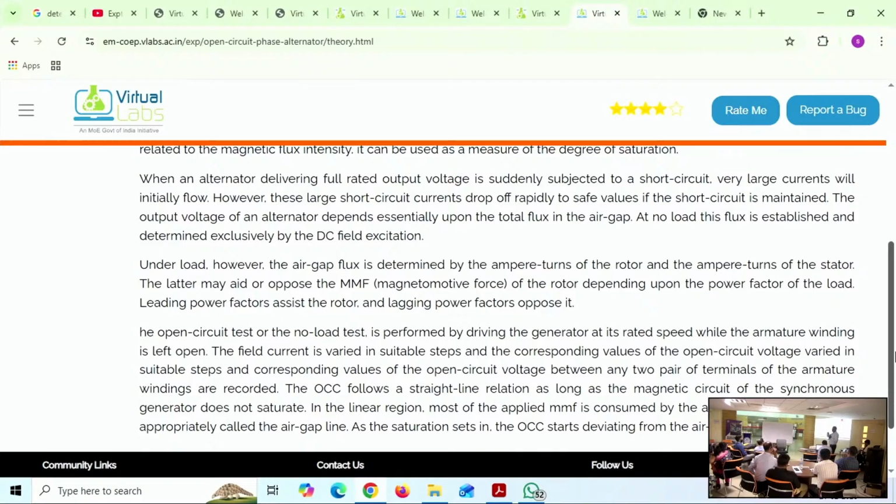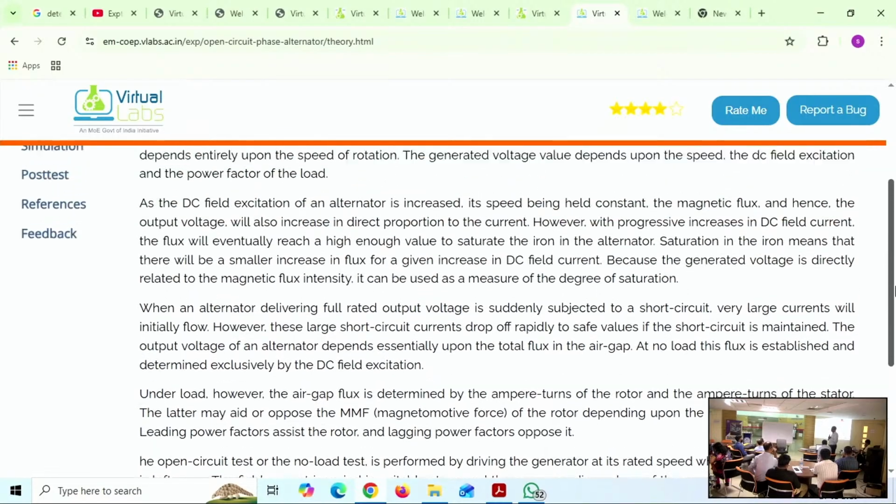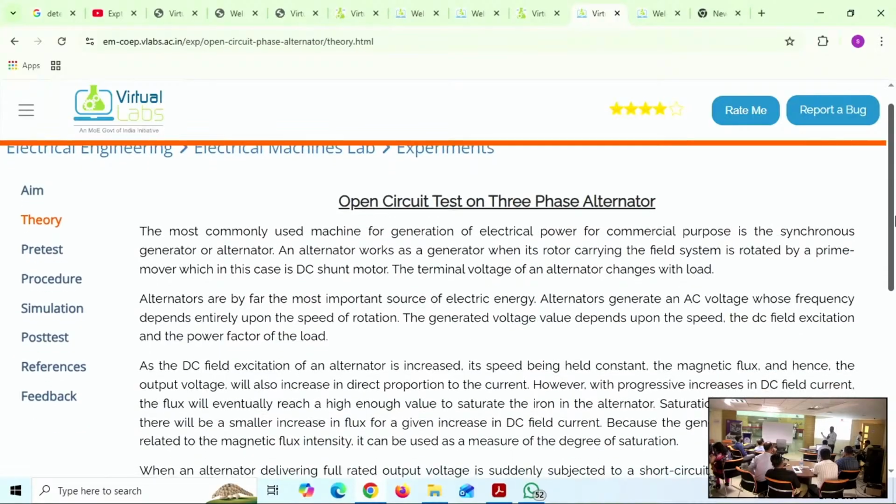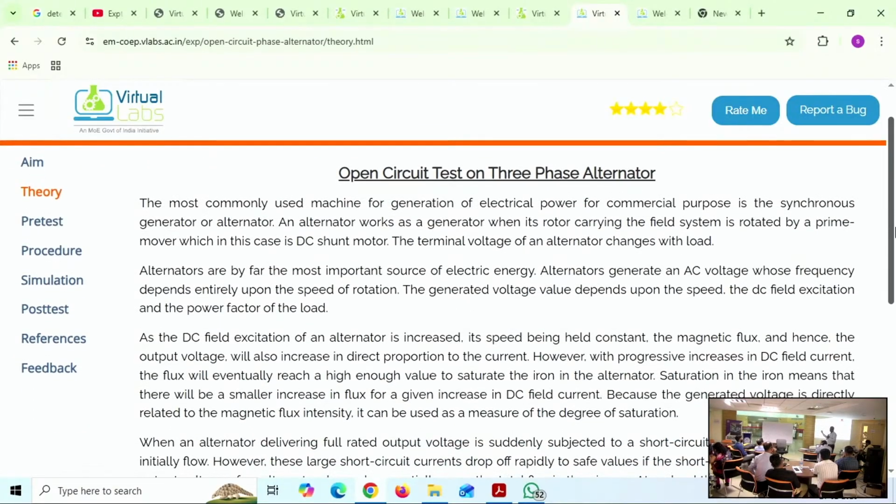That is how we better understand the experiments. One more thing, while connecting the meters: theoretically, ammeters must always be connected in series and voltmeters in parallel. Now practically, first we take the supply phase positive, and immediately we connect it to the positive terminal of the ammeter or the positive terminal of the voltmeter. Which should be connected first? Who should come first, ammeter or voltmeter, or can it be either?